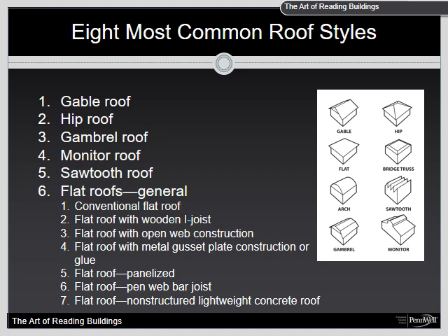Rafter joists in conventional flat roof configurations may or may not have internal, horizontal, and/or vertical support. The primary method for connecting structural members is a metal plate and bolt and/or nails. Some older roofs have bridging or scissor bracing between the joists to increase lateral stability. On-center spacing for rafters is typically 2 feet.